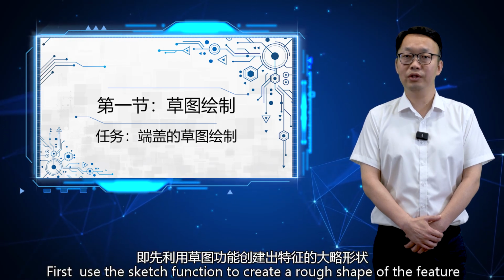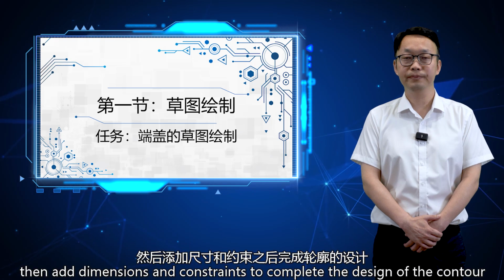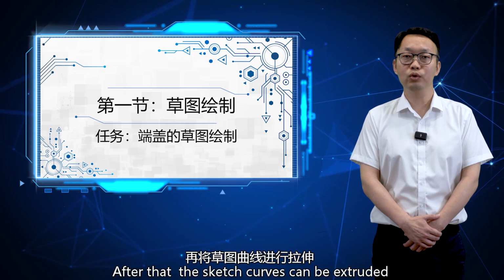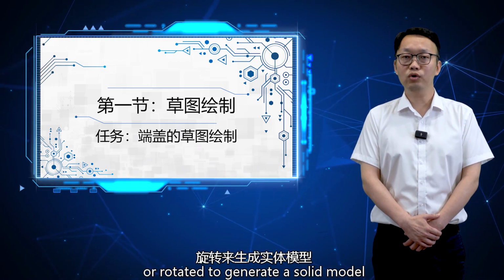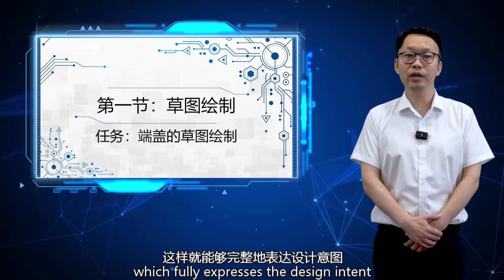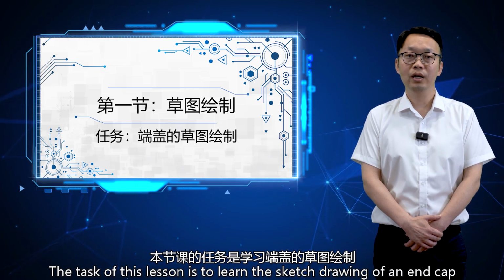First, use the sketch function to create a rough shape of the feature. Then, add dimensions and constraints to complete the design of the contour. After that, the sketch curves can be extruded or rotated to generate a solid model, which fully expresses design intent. The task of this lesson is to learn the sketch drawing of an end cap.